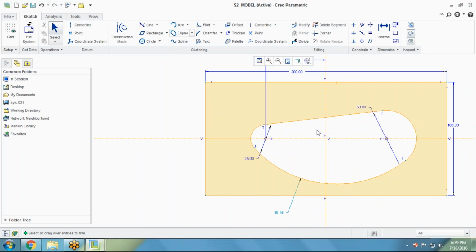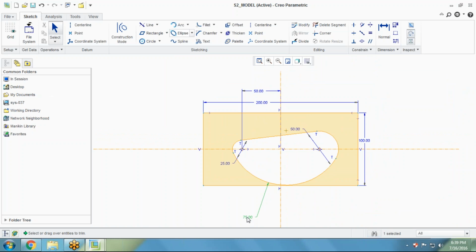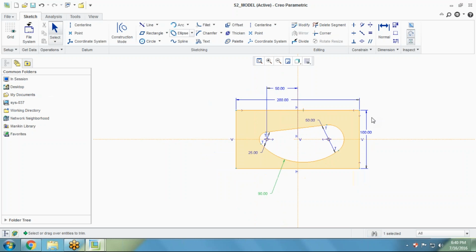Delete them. Now you will see there the object is in some different shape, and now the value we can define. The value I need to provide there is around 75. Then you will see there the object will be wider in size. If I give the value 90 millimeter, this will be looking like this. So you can change the values according to your need after creating the tangential option and after deleting the segments. And now we will create some more sections there according to our need.